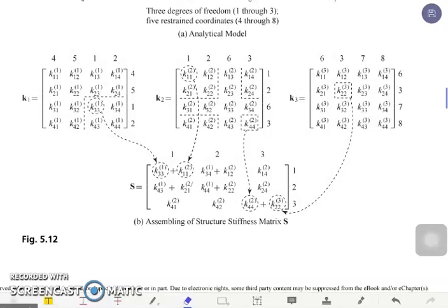For the beam, we don't have a transformation matrix, meaning we don't have member forces in the global coordinate system, since the members of the beam are directed in one direction. Unlike plane truss, where the members are not directed in one direction, because there are members that are horizontal, vertical, or inclined, for the beam the members are directed in only one direction. For example, in our illustration, we have the horizontal direction. That is the direction for our members of the beam.